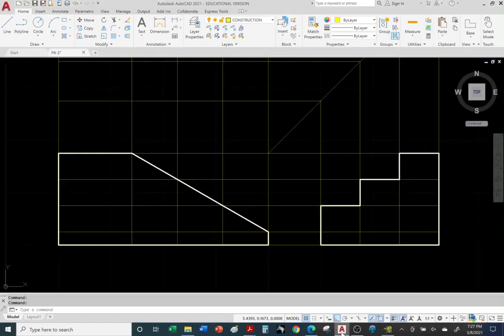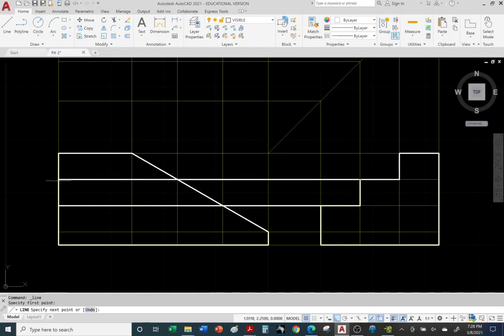Be pretty straightforward. Okay, so let's go to the visible object layer and use the line command and just go to the corners, project across. I'll go ahead and draw across. You want to have ortho on, guarantees a horizontal or vertical unless it snaps to something. Okay, and right click enter, and then we'll go to the other corner. There it is, right click enter.